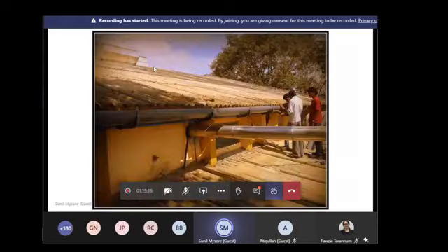Actually, you have to be a little careful in the detailing of the gutter, because if the gutters are not fixed properly, because of surface tension of water, all the water can just go out. If you observe, when the water falls from the sloping surface, it sticks to the walls, so it takes a turn of a couple of inches and then falls down. If you don't detail the gutter properly, you are going to lose a lot of water because of surface tension.